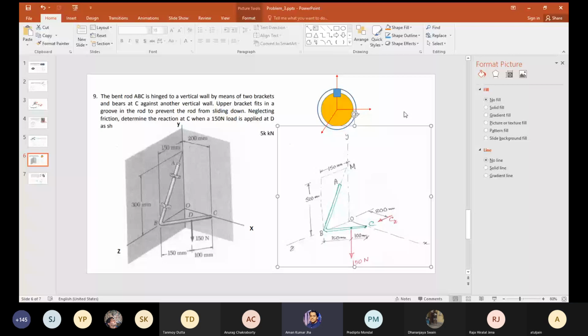Sir, the arrangement of AB is like the previous question, no? Two rings with a pencil. Yes. But two rings with a pencil, and in one of the rings we are also putting a perpendicular slot so that it cannot move. That is the groove. In that upper groove, there will be only movement about AB. Translation along the three axes is not possible. Rotation is possible. But in the previous one, about one axis, the rotation is not possible.